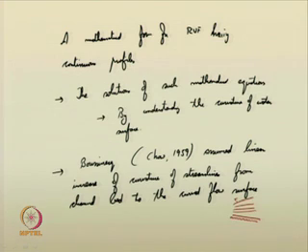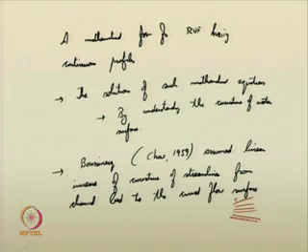The curvature of the flow profile increases linearly with respect to the depth. That was a simple assumption incorporated by Boussinesq, and he then analyzed the fluid flow for rapidly varying conditions. They use the momentum equations to solve such fluid flow problems.